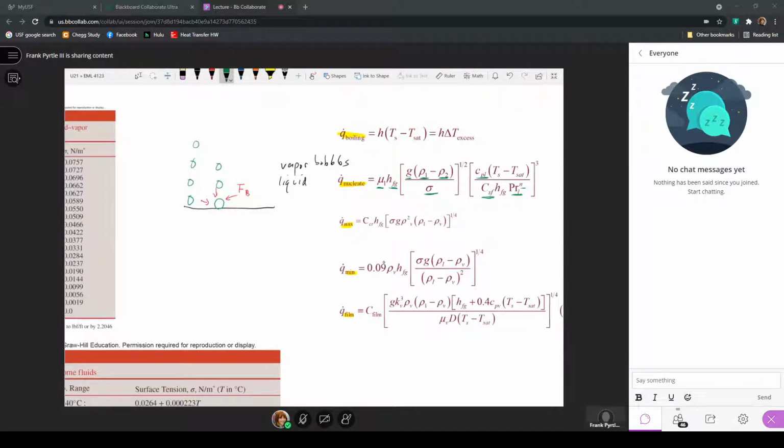And for the heat transfer from this surface, whether there are bubbles forming all over the surface or only at particular points along the surface, there would be fluid moving over this surface, so that there would be a heat transfer coefficient associated with not only the change in phase of the liquid to a vapor to produce these bubbles, but also all of this fluid moving over the surface. So this expression for a heat flux in the nucleate pool boiling range takes into account not only the latent heat of vaporization that is removed from this surface, but also just the general movement of the fluid.